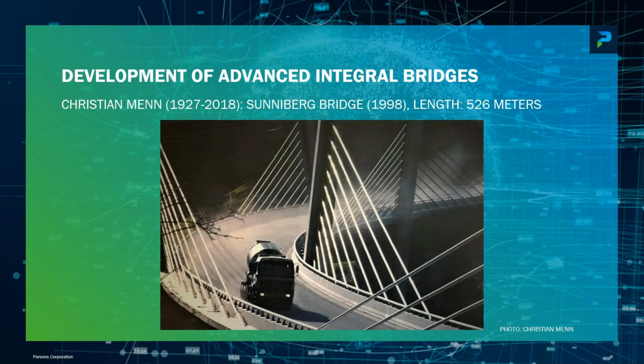These bridges breathe like your tummy is breathing when you take air in and out. And this way, they reduce the restraining effects. In order to facilitate this breathing, the piers need to be accordingly shaped so that they are flexible. But on the other hand, through the integral abutments, the superstructure provides lateral support to the piers. So everything works together. The piers help the superstructure and the superstructure helps the piers. And that shows you the overall design philosophy.